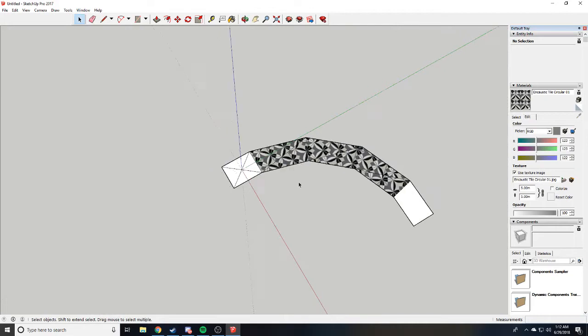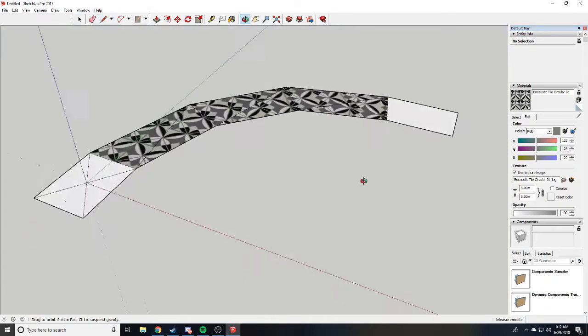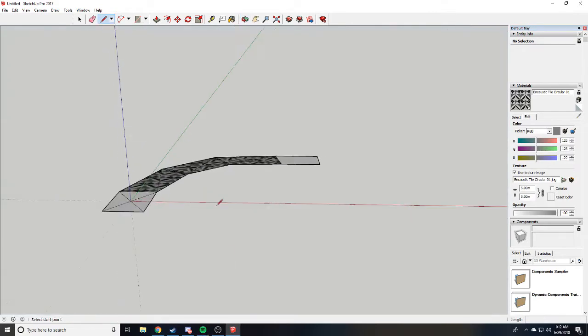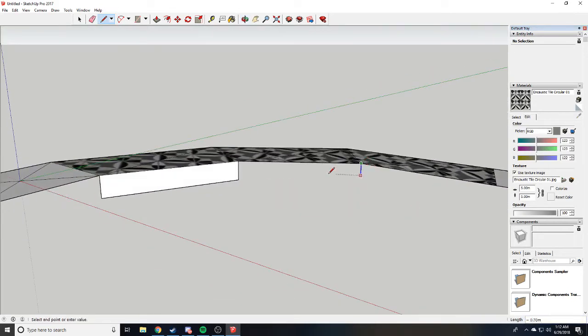So let's say now, what if you want to make this have some depth? What if you want your slide to be not so flat so that you can see through the bottom? It's also very easy. You just take, once again, you want to press up arrow key and go to each point along each side and draw a line down. I suggest keeping it to a similar height all the way through. You can do that by typing the height and then pressing enter. So just going through each point and adding